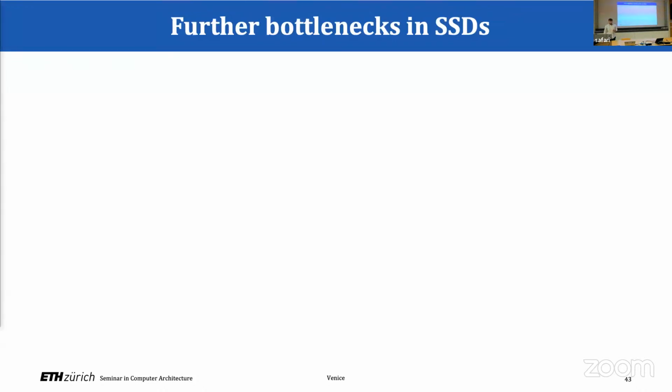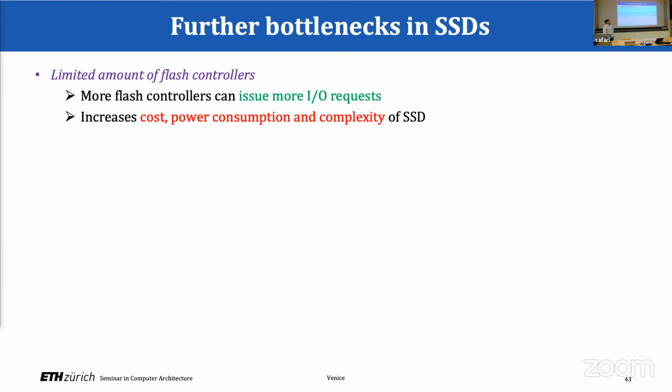Yeah. So one thing that I noted is the limited amount of flash controllers. Could anyone think of some benefits or disadvantages of increasing the number of flash controllers? I mean, one obvious benefit of having more flash controllers would be that we can issue more IO requests in parallel and we can get more work done, but that would also incur a higher cost in the architecture itself.